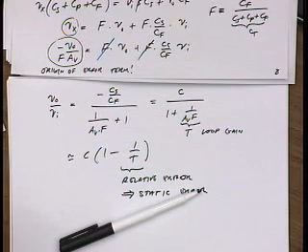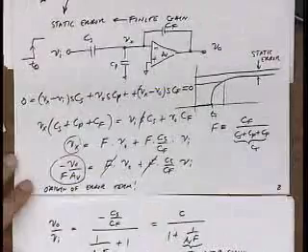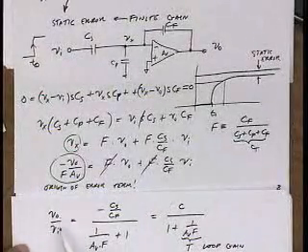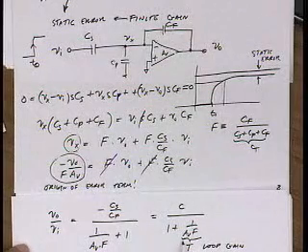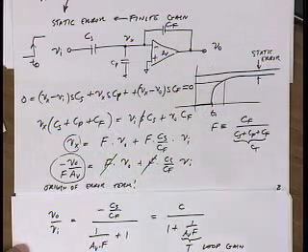Okay, Shiji, why is it a large signal gain? When we develop an equation, we actually use V naught divided by open loop gain. So V naught is a large signal divided by open. If you go back and look at this analysis, nowhere did we make a small signal approximation, right? So really, this is V out over V in. AV is V out over Vx. It's not dV out over dVx. So AV is the large signal gain.